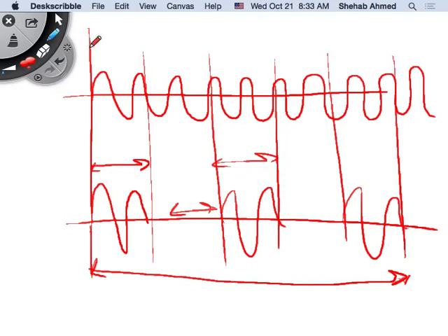In that case, it's better to use phase angle control and just, within the whole initial sine wave, only turn on the thyristors in these parts. Right? Provide an alpha here and an alpha here. That way, you're only applying a very small amount of voltage to the motor's windings initially. And then you move alpha back. So alpha will change, you can change it from 180 degrees all the way to 0. After you change it to 0, you've put in all the voltage across the motor. And the motor was designed for this 50 hertz and this full voltage. Then the motor can provide full torque at that moment.